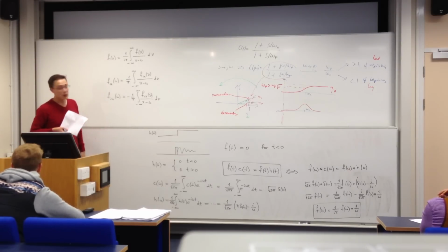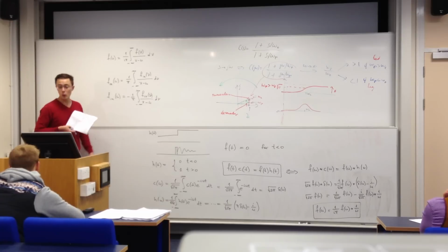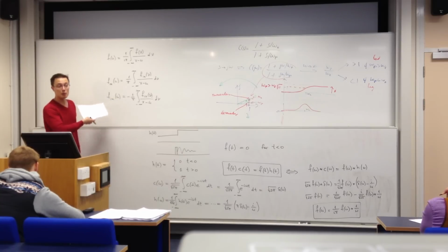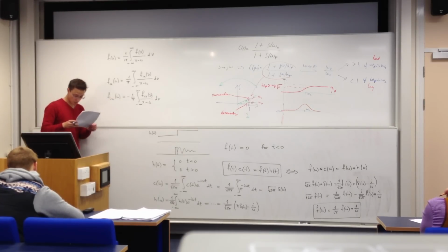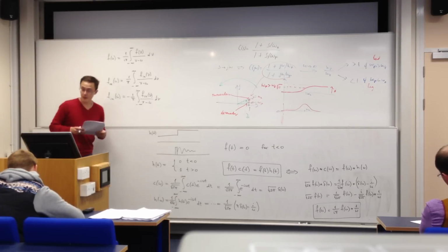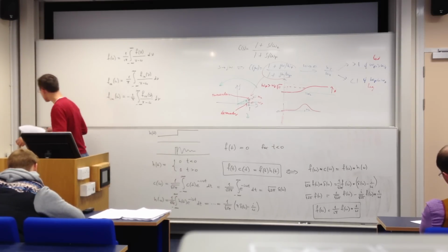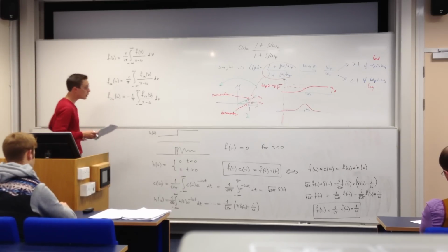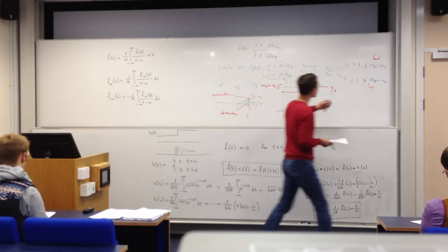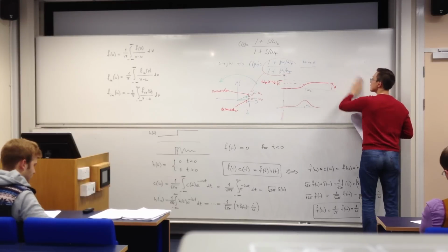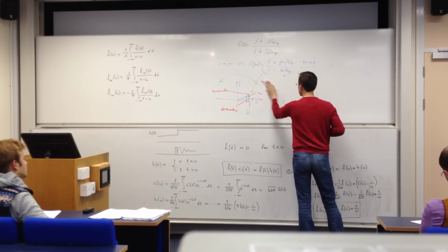So bear this equation in mind. You will have to use it, or rather you will have to tell MATLAB to use it, which is a fair bit easier, to reconstruct your imaginary part for phasing before you actually fit those spectra. And these two things are also known in the trade as Kramers-Kronig relations. They can be derived from different considerations from the ones that I have given. Different textbooks do it in a different way, but they are very useful in that they relate the real and the imaginary part of the response signal of any linear time invariant system.